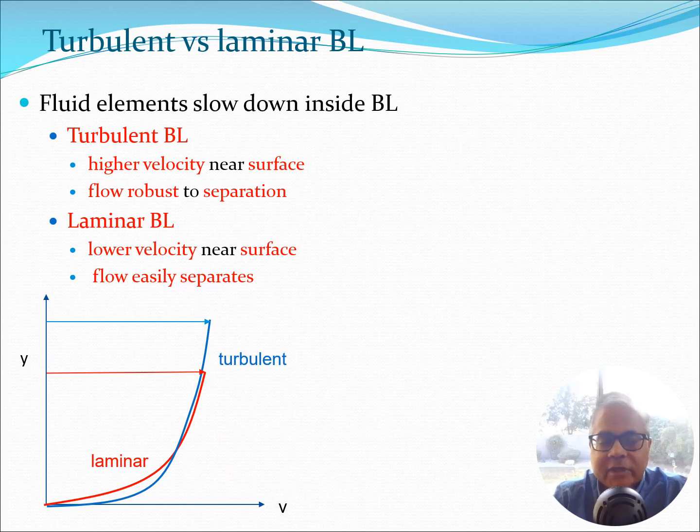Now in a previous lecture I showed different pressure distributions and how you can tailor the pressure distribution so that you can hold laminar flow for a longer time for a given airfoil section. If you want to look at that, go to the previous lecture and take a look at those types of airfoil sections, which essentially have the highest thickness somewhere near the mid chord region.